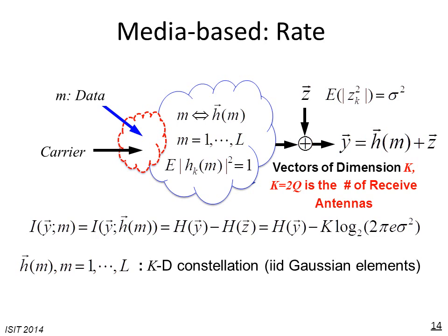Now, one point that I would like to clarify here: the fact that we end up with a constellation with IID Gaussian components essentially aligns with the requirement of random coding over an additive white Gaussian noise channel. So it's a desirable feature. And as we will see, this feature eventually, asymptotically converts the channel into an AWGN channel.